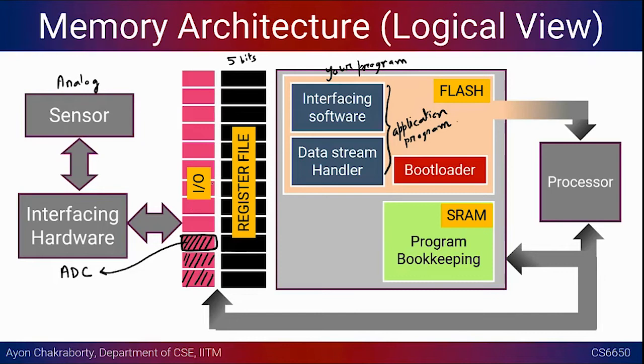And then there is this EEPROM, which is non-volatile storage also, but it's not used as frequently as the flash memory, the input-output registers, the register file, and the SRAM. Suppose you want to have something statically stored, let's say a company logo, that you want to load from time to time. It's like the splash screens you often have in Android applications.